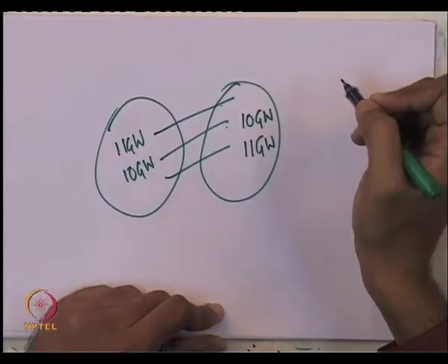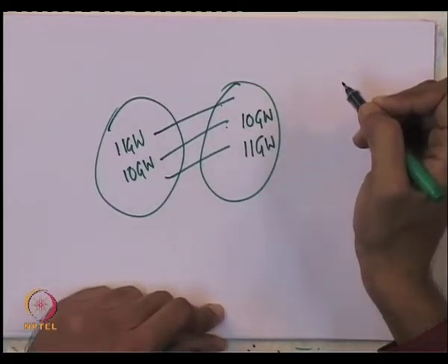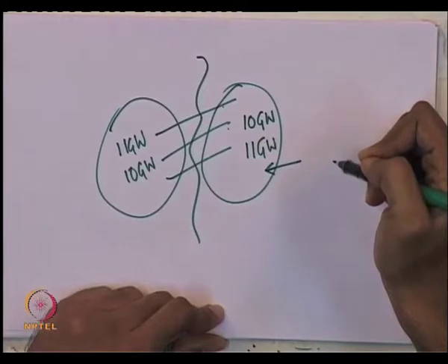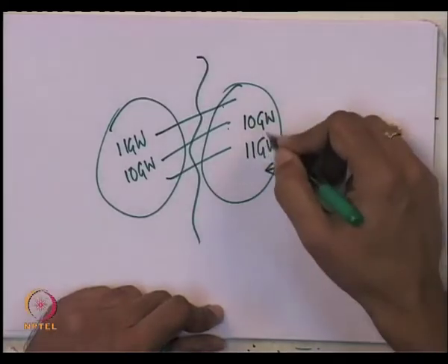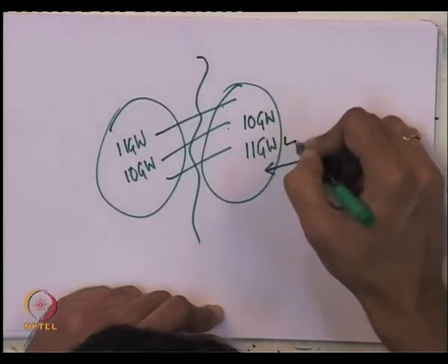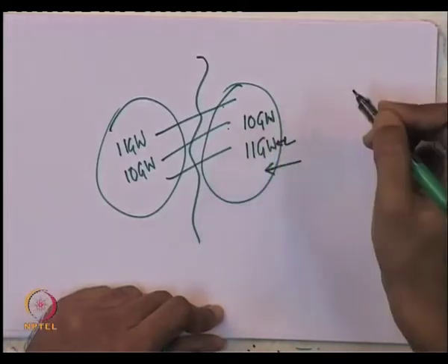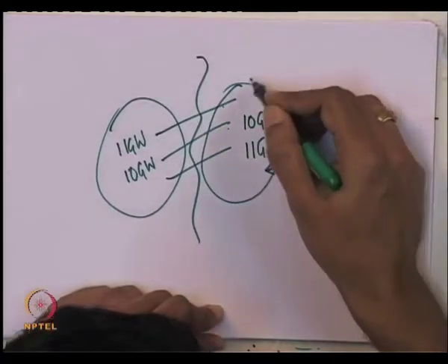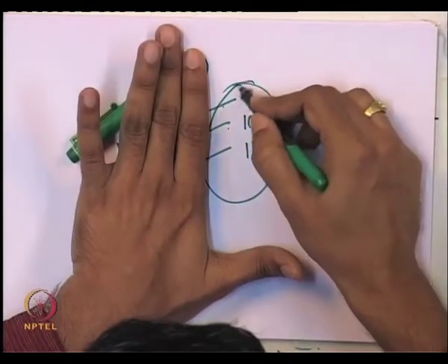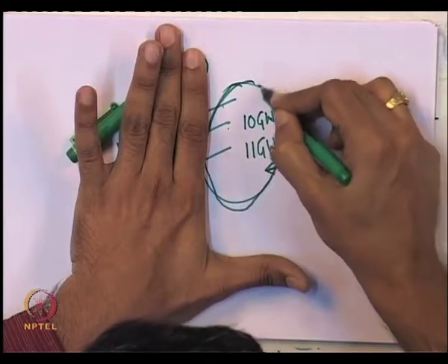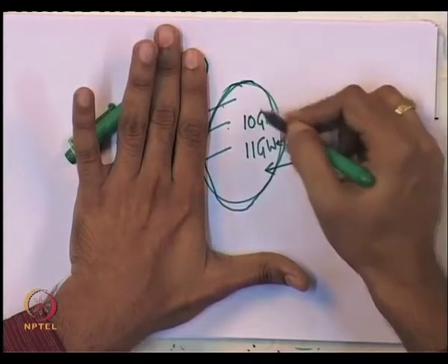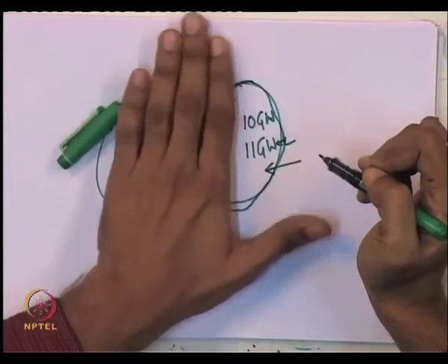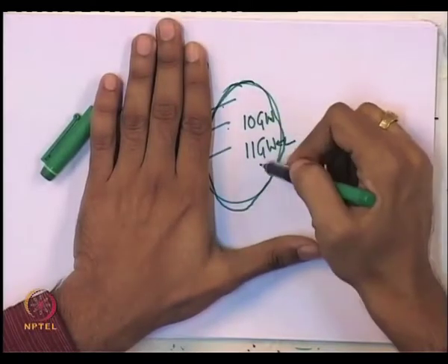In that case, if because of some disturbance there is a loss of synchronism and you separate out these two systems, then this system will be an under generated island. There is a load generation imbalance and you will have to trip out some load to get this load generation balance. One of the ways you can do it is compute the center of inertia speed of this particular system once you separate out. So, something which your central computer which is computing the center of inertia needs to know is which are the generators in this island. So, you need to know that. This is one issue.